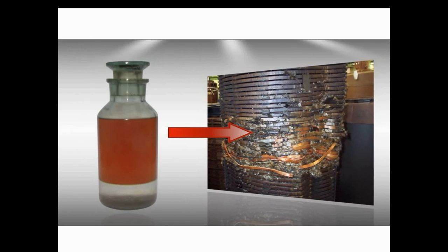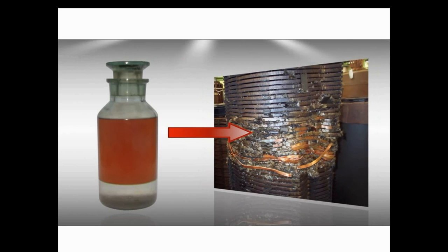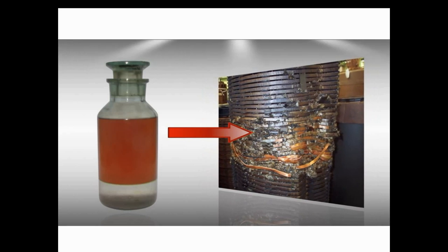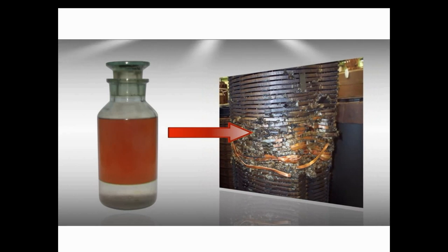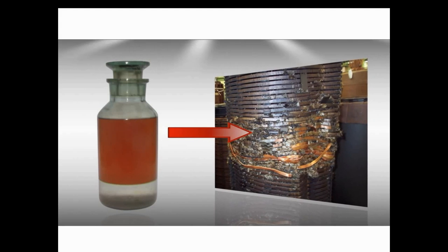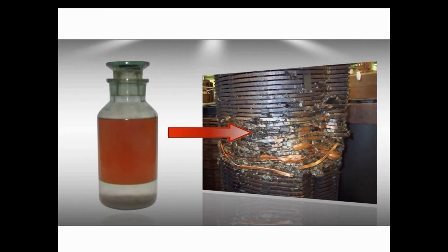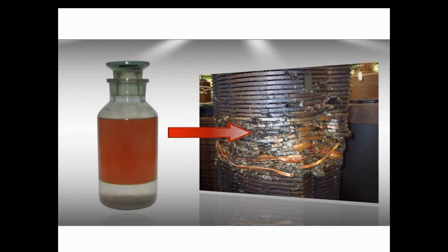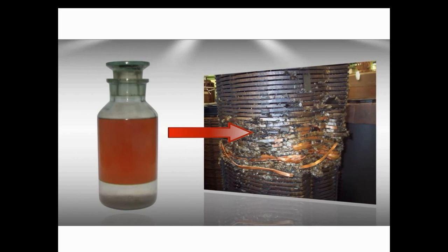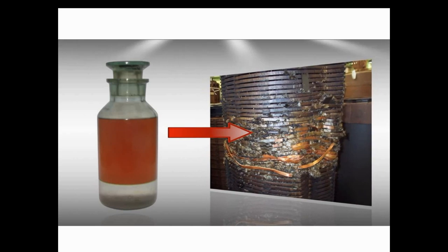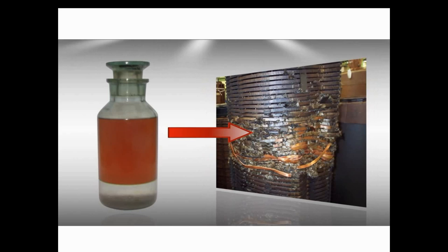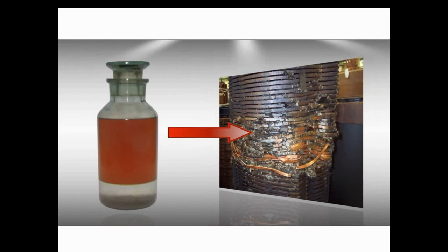97% of water is in the transformer paper insulation. Oil purification is not a transformer drying out, as it removes water from the oil but not from the windings. It's impossible to take an oil purification machine, bring it to a transformer and dry it out in one day, as the moisture is accumulated deeply in the paper insulation.